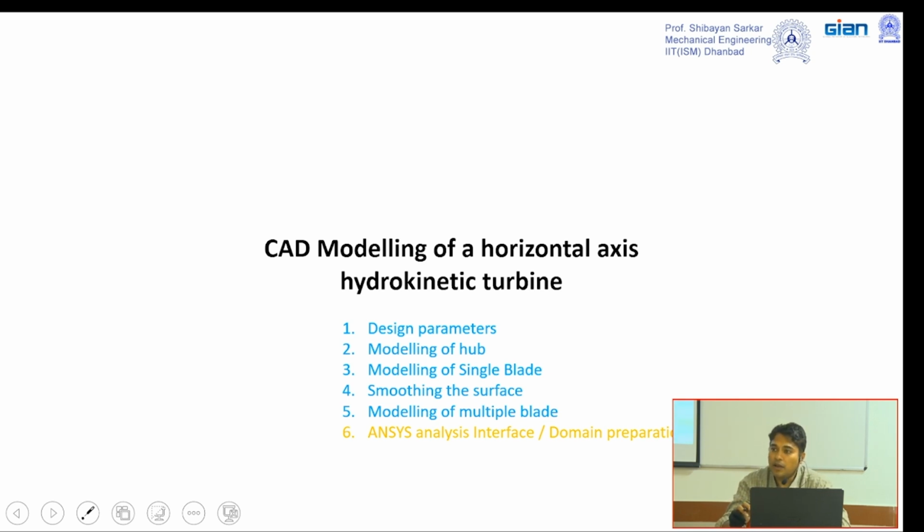All these problems can be taken care of if I place an axial turbine. An axial turbine's blade will be like this. Suppose here there is a fluid flow velocity of, say, 1.1 magnitude, and suppose in this portion it is 1 magnitude. Whenever this blade rotates here and comes out here, it gets the 1.1. At least each and every blade will encounter the same velocity at a time during the rotation, and this particular tilting problem will not occur.